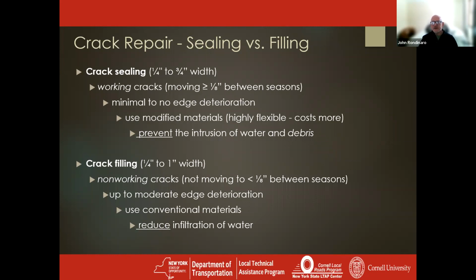We're doing all our snow and ice control efforts, but you're pushing a lot of junk down into that wide open crack. Then as the temperature rises and the crack tightens up, you're crushing that debris, and you're also crushing the sidewall of the crack, greatly advancing the deterioration and taking it from a nice, clean crack to a really nasty looking crack.